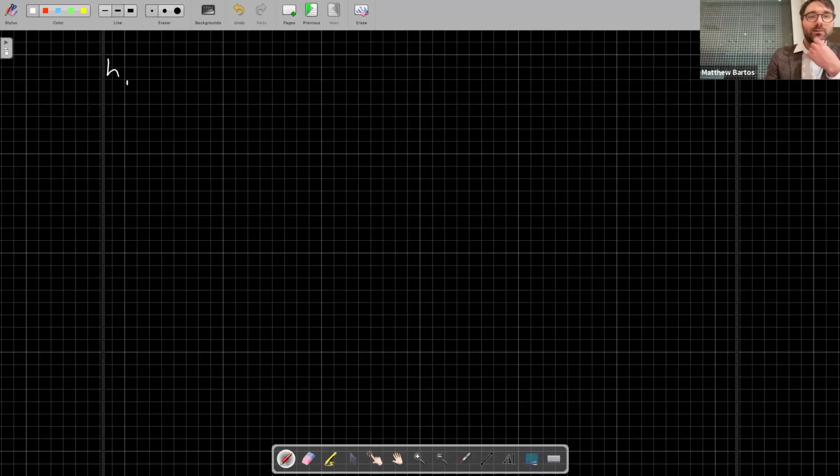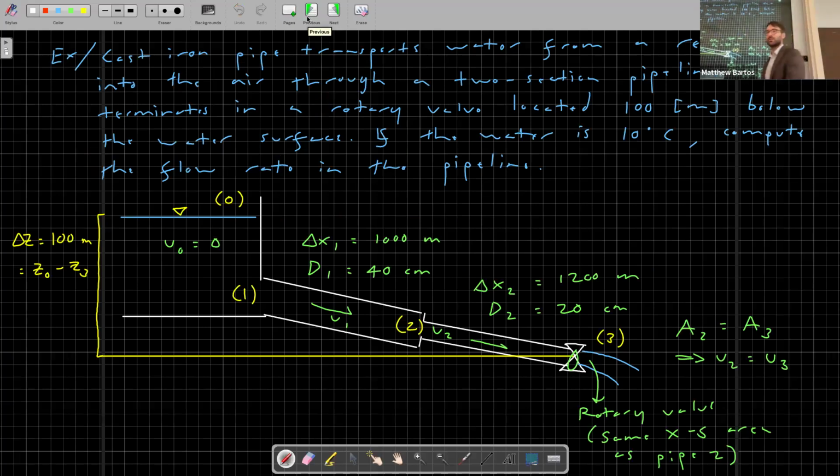So how can we determine our major losses here? What equation do you think we should use here? Darcy-Weisbach. Because the problem statement gives the temperature, you probably want to use Darcy-Weisbach because Darcy-Weisbach is the only equation that accounts for the temperature and the viscosity. So for this class in general, unless otherwise stated, use Darcy-Weisbach to compute frictional losses.